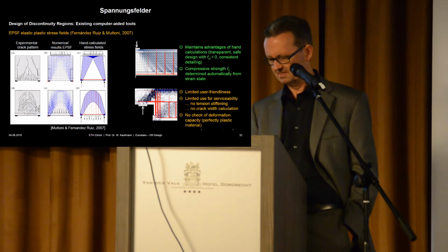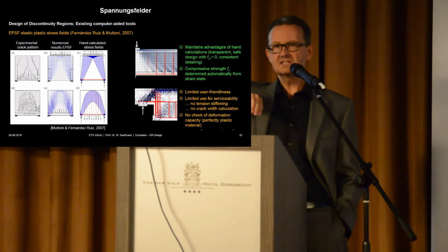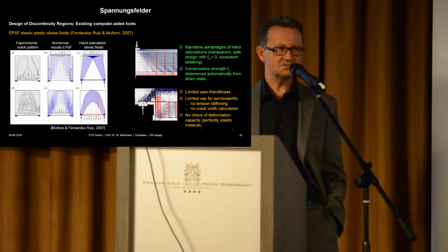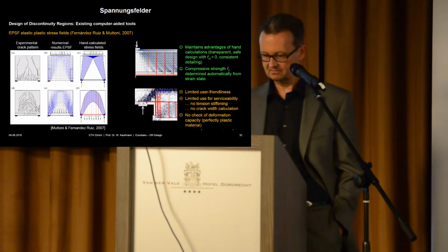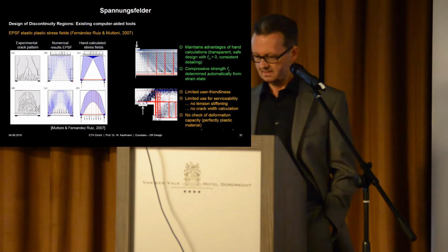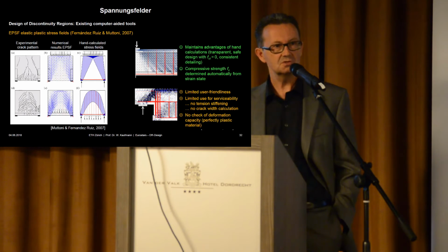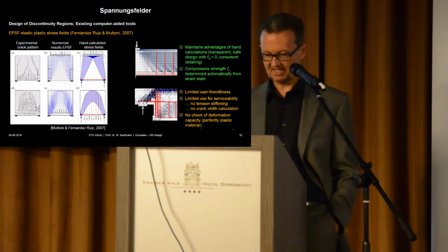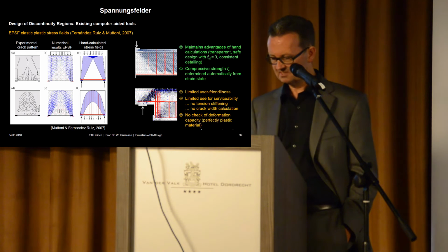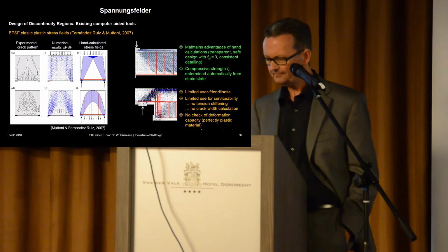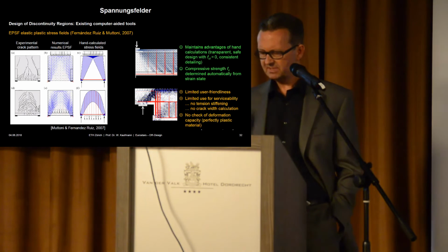Let's put it this way, to be consistent. So they neglect the tensile strength, and on the compression side, they have linear elastic, ideal elastic. So they don't have any tensile strength in the resistance, which is great. And they can determine the compressive strength from the strain state at each point of the structure. So you don't have to manually input KC factors. So we think that's really good, and we wanted to maintain this also in the StatiCa Detail. But it is kind of limited user friendliness.